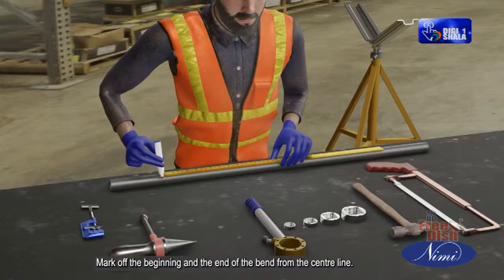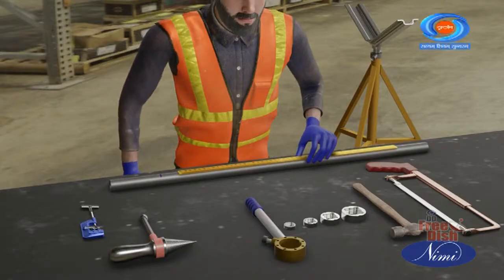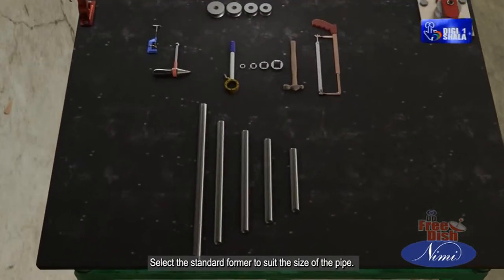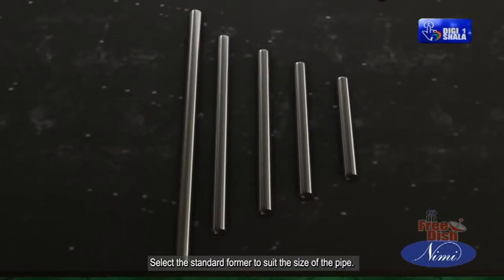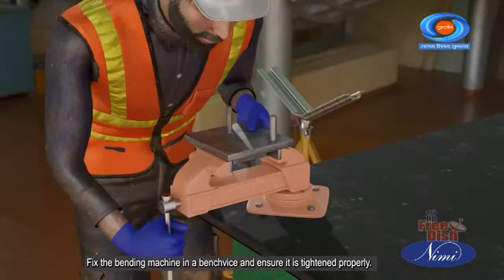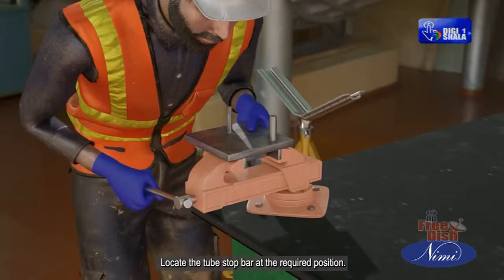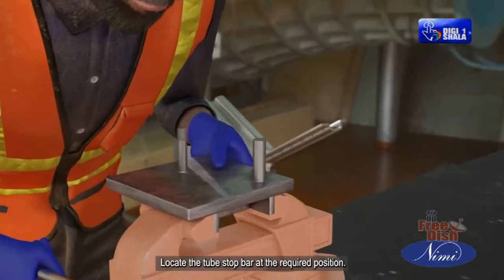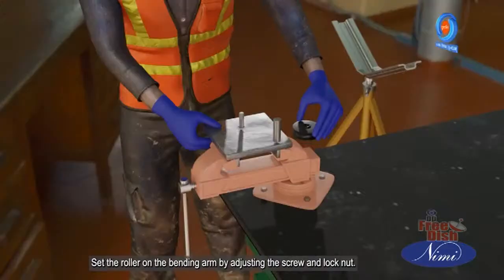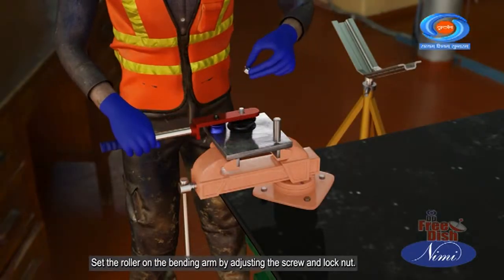Mark off the beginning and the end of the bend from the center line. Select the standard former to suit the size of the pipe. Fix the bending machine in a bench vise and ensure it is tightened properly. Locate the tube stop bar at the required position. Set the roller on the bending arm by adjusting the screw and lock nut.